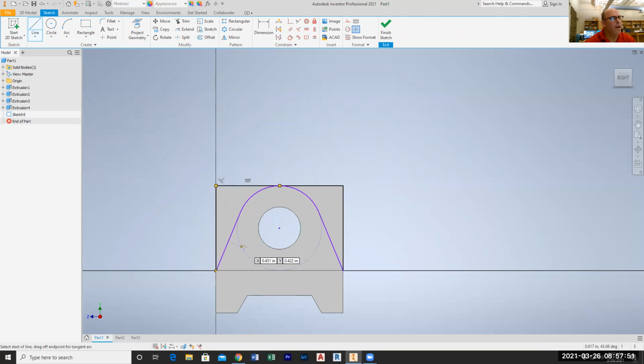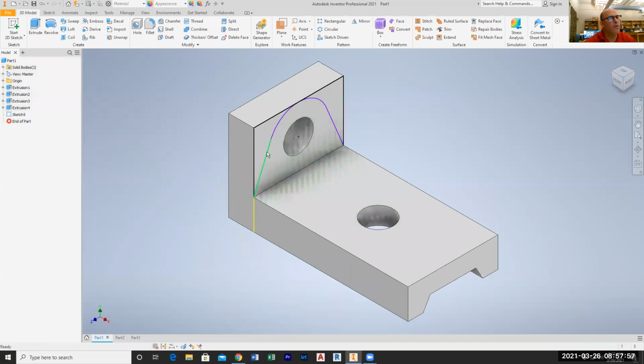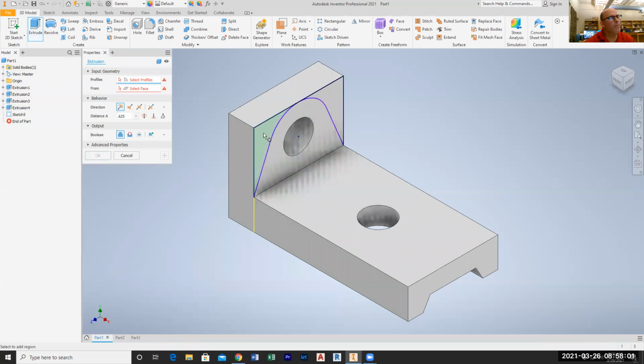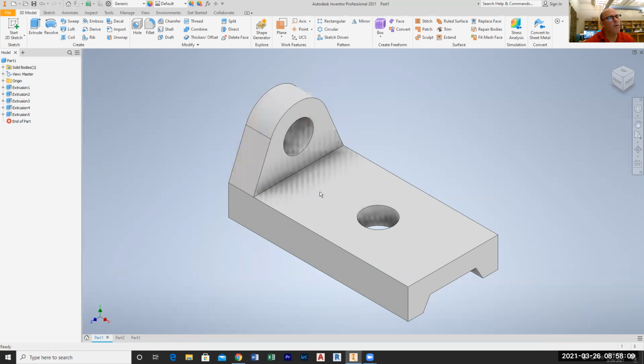And now I have that totally enclosed. So if I finish that sketch right here, I'm going to go ahead and try to extrude. Hopefully this works. Extrude that part, let's go this direction, okay? Extrude that part that direction too, okay. And there's my completed object.